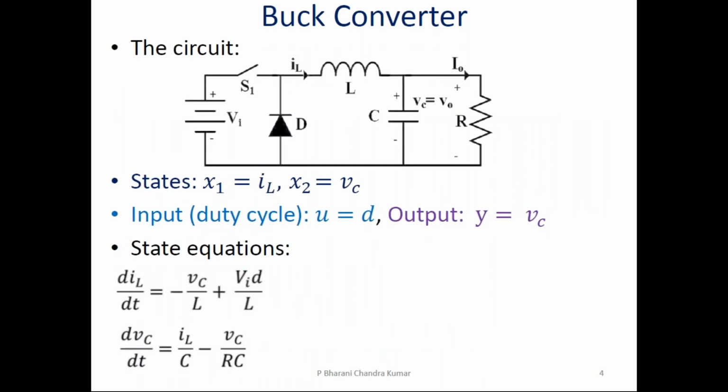So this is the fundamental circuit for the buck converter. For ages, people have been using the same buck converter, with no change. This is the input DC voltage, and this is a switch. This switch can be realized using various devices, generally MOSFETs or IGBTs, which are the most preferred due to their fast switching nature. And this is the inductor, this is the capacitance, this is the load resistance, and this is called a freewheeling diode. There could be two types of equations you can get from here: once the switch is on, or once the switch is off.